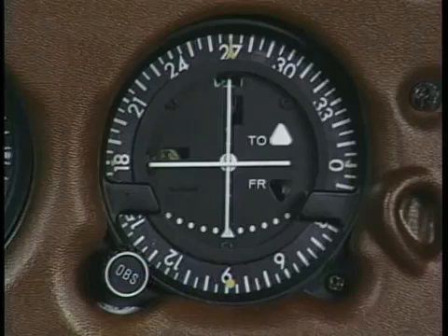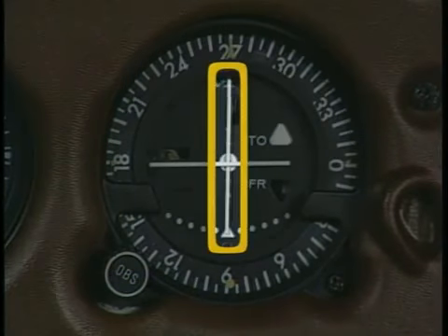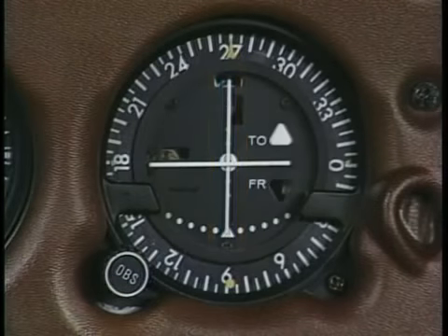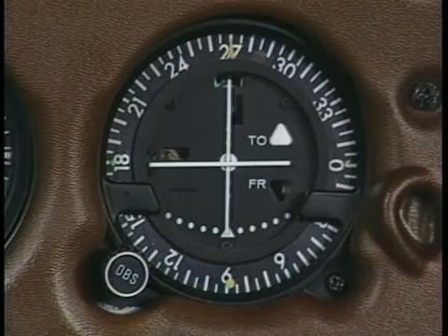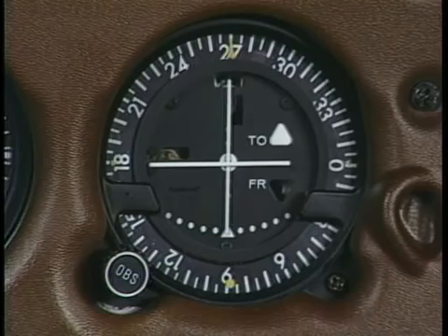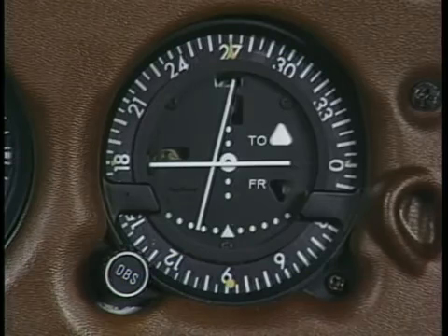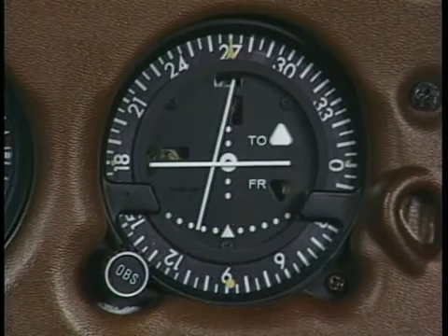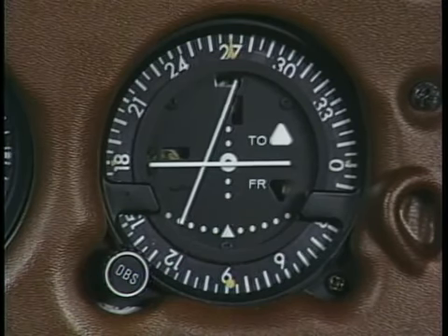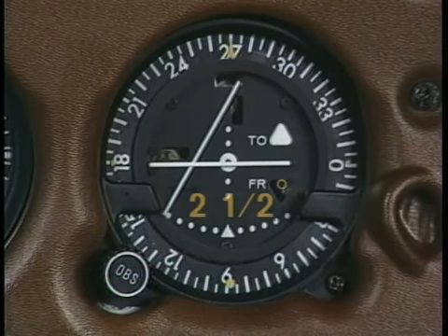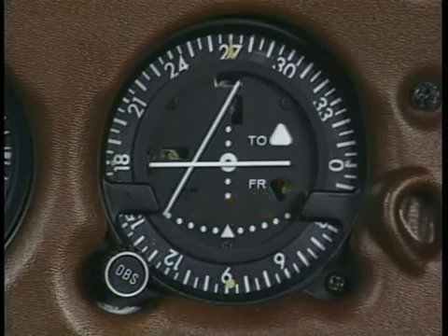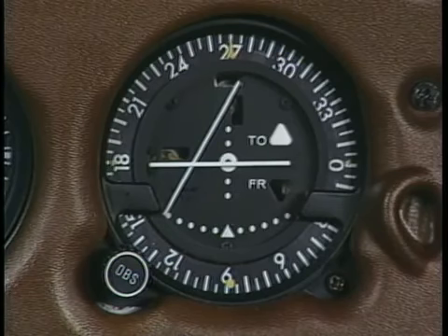Inside the cabin, course guidance is provided by the course deviation indicator on your VOR equipment. When you are flying inbound along the front course, the CDI tells you if you're drifting left or right of the runway center line in much the same way as when flying along an airway. However, with an ILS, the instrument is much more sensitive. On a typical ILS, full-scale deflection occurs at 2.5 degrees rather than the normal 10 degrees with VOR. Theoretically, then, you should be able to track the localizer course 4 times more accurately than a VOR radial.